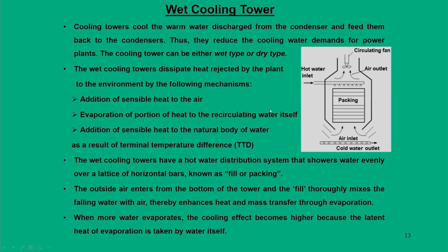So, what we look at in a wet cooling tower concept is, if you look at the figure here, the hot water inlet comes, which normally comes from the exhaust of the turbine, and it is sprayed. When it is sprayed, it passes through a packing or fill.